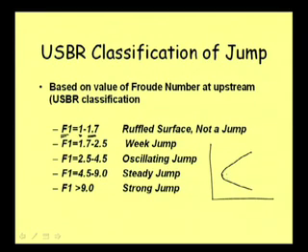Well, when we have depth at this level, it is more supercritical. Critical depth is this one, yc. So, when our depth is much less than critical depth, the Froude number is increasing. As we are moving in this direction, that is, our depth is decreasing, the Froude number is increasing when it is in the supercritical zone.